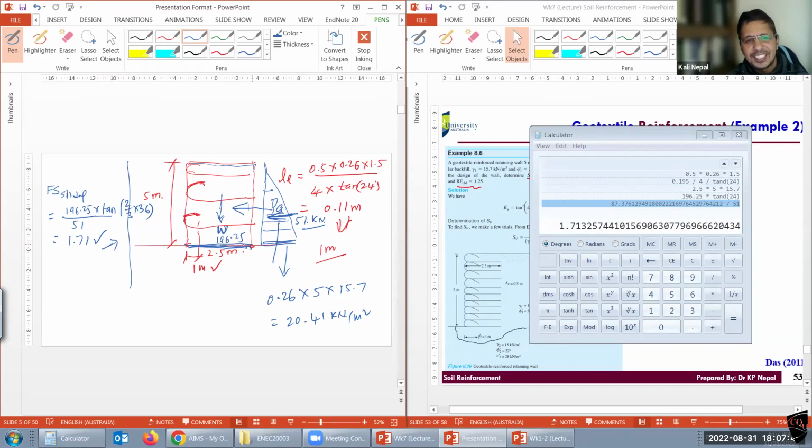Because the length of the block is small, right? 2.5. Previously, we had what? 13 meter long, yeah? That's why it was more stable. So I would recommend not 2.5 now, maybe go 3. Yeah, 3 meter, right? So that it will be a little bit safer.